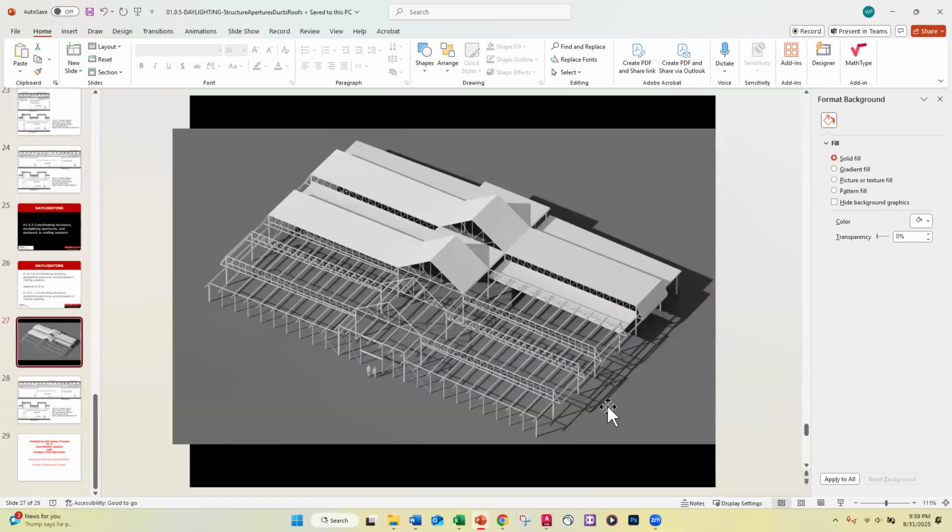Some of the drawings I'm going to present, which are related to assignment 5, will show corrugated decking, and as long as it will span the space between the trusses, that's a structurally legitimate way to do things.